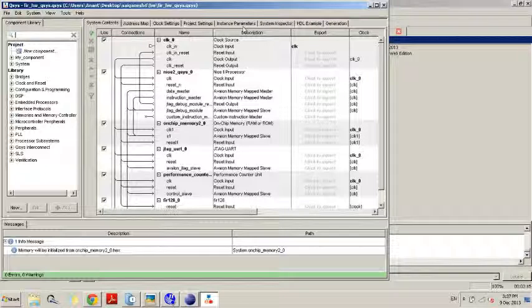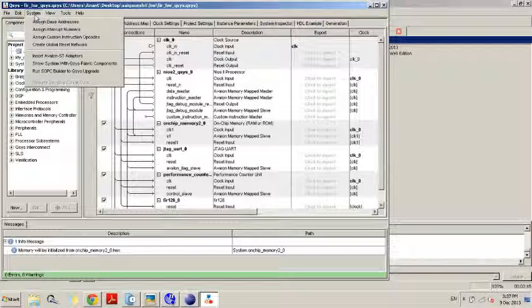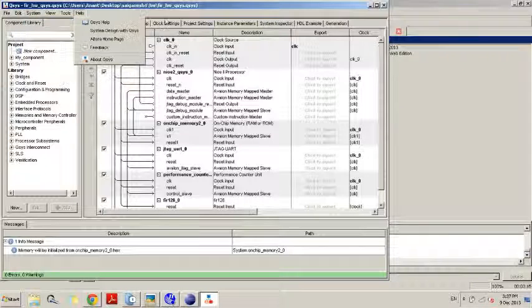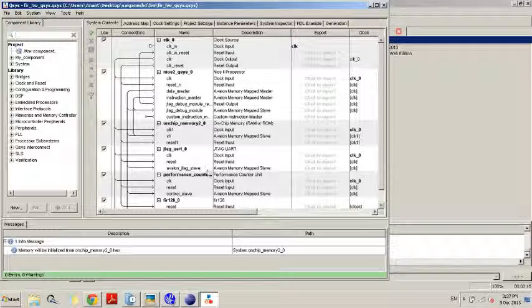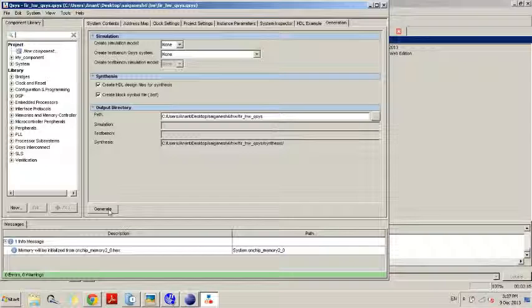Make sure you do the assign base addresses step before you hit generate. This would make a proper base address generation. Then the second step is the one which I have mentioned just now. Go to the Nios processor and select the reset and exception vectors to be that of on-chip memory. Then you have to click generate. Since the generation takes a lot of time, I have already generated the file which has the extension .qsys.